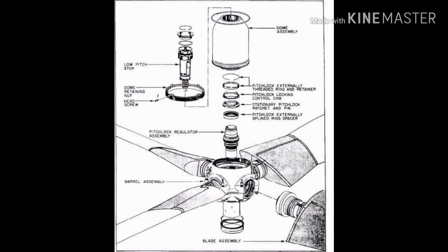High pitch pin malfunction. Feathering propellers that use air and spring pressure to feather the blades have spring-loaded, high-pitch stop pins that prevent the blades from feathering every time the engine is shut down. In flight, the high propeller RPM causes centrifugal force to move the pins out. The cause of high pitch pin malfunction is the same as high friction in hub parts, which is corrosion.